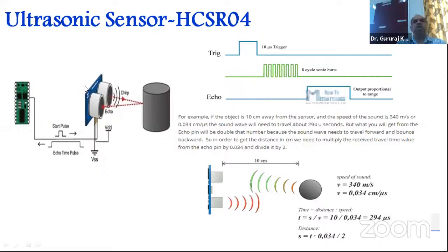As it keeps emitting, the other one will receive the signal and constantly measure the distance, every now and then. If at any time this Arduino board receives signals within the 10 centimeters, the board computes this value, and if it is within that 10 centimeter range, it will generate an alert to the end user. It may be a buzzer sound, a display on the monitor, or some other sort of alert generated using these ultrasonic sensors.